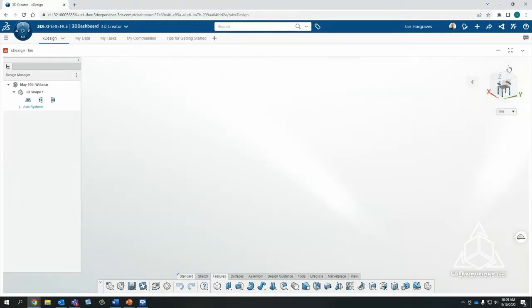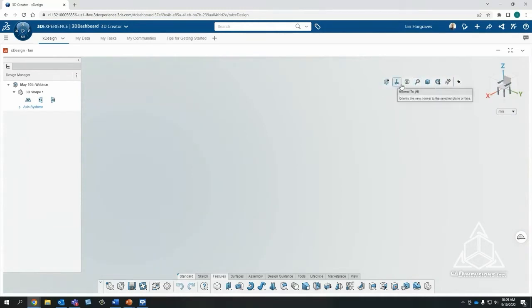So if I wanted to go to the bottom view, I could rotate there, click that, and see what the bottom view is. I can also do the clockwise and counterclockwise too. I'll keep that kind of the parametric. I also have some tools for viewing, so I can do normal, zoom, fit, all that kind of stuff. You can pin it, but I usually just leave it off. Underneath that, we do have our units. I'll be working in millimeters, but you can switch on the fly. So if you work with millimeters and you need to switch to inches, you can always just switch that there.